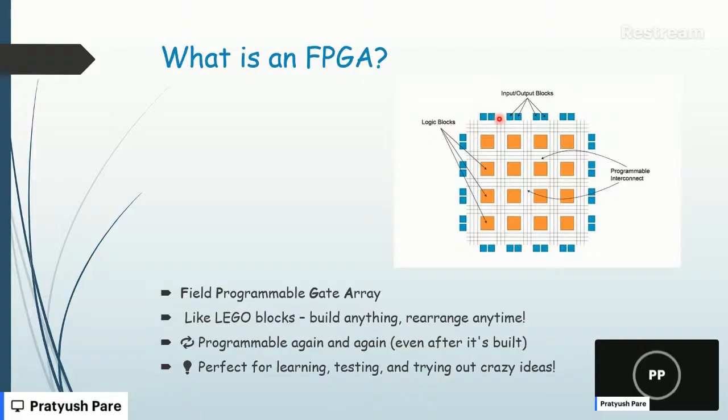So in FPGA, there are different logic blocks which are present, and these logic blocks are programmable. Consider these as wires. When you write a design file and give it to the synthesis tool, like let's say you are using Quartus for synthesizing your design for an Intel FPGA module, it generates a bit file, a series of zeros and ones. Those zeros and ones come to these wires, and these wires program the logic. This programming is done in such a way that it programs the FPGA for your purpose.